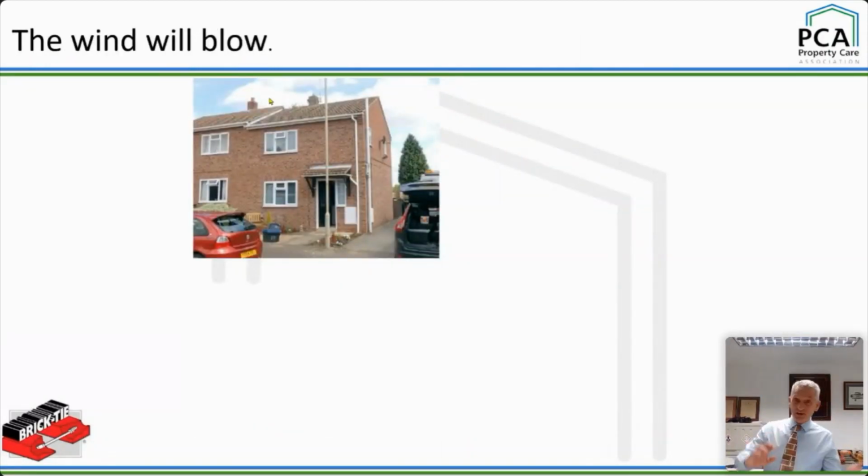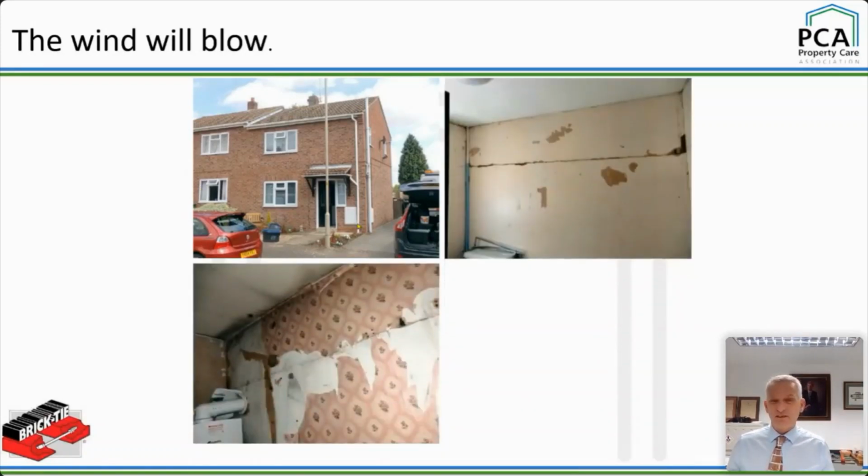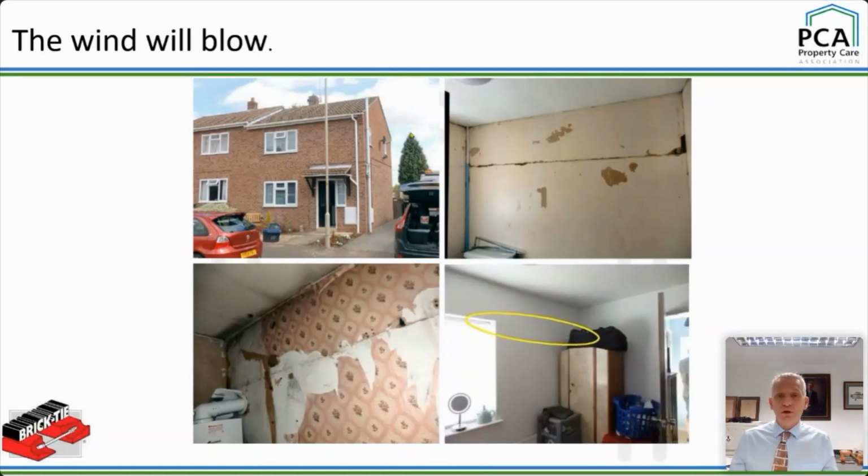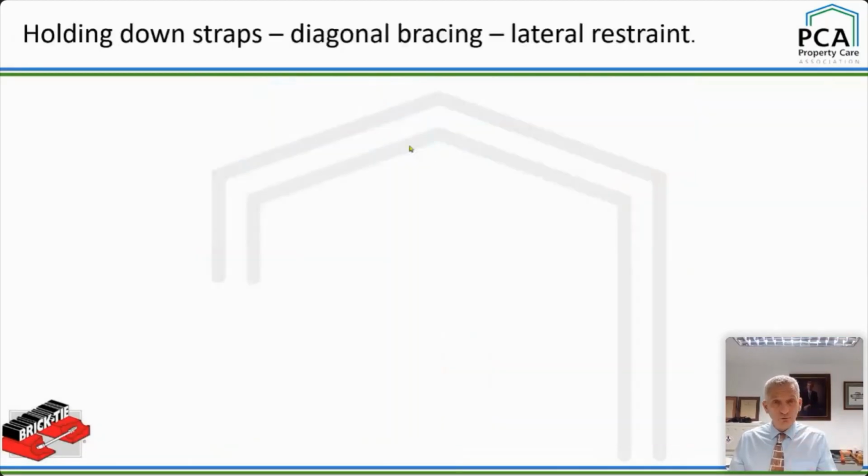Now then, back to surveying. So I know we're up and down all over the place, but it's important because we've got a lot to cover. So look at that house, post-war, 70s, 80s. Apex is bulging out a little bit. Go inside. This is after it was stripped off, but basically we've got these cracks running around the front and rear walls. They're not on the side walls. They come through. That was one on the survey, so you can see the cracks come through the paper.